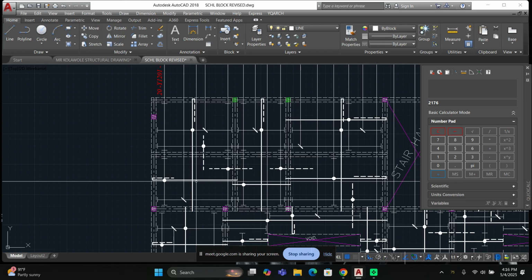So now it said all floor slab main bars is 200 mm, right? The continuous edge is 250. Then it said ground floor beams, first floor and typical second, third at 600 depth, roof beam at 350, beam provision to follow soon.